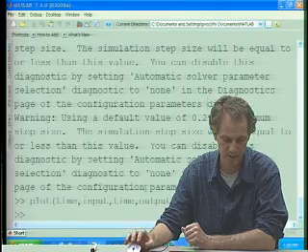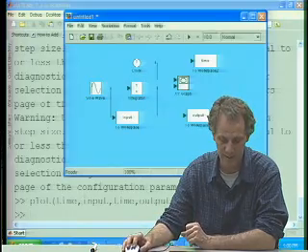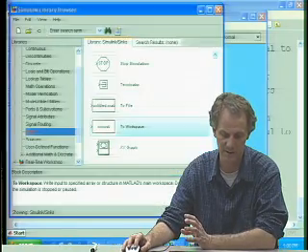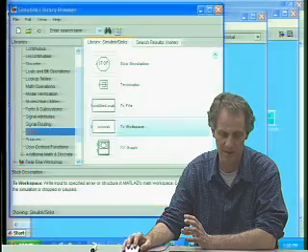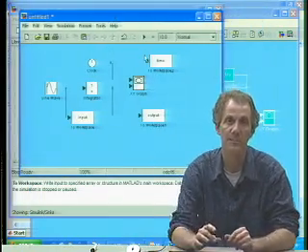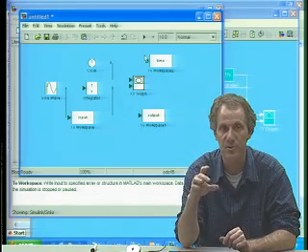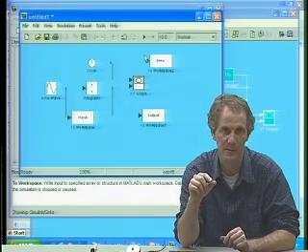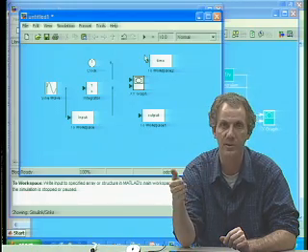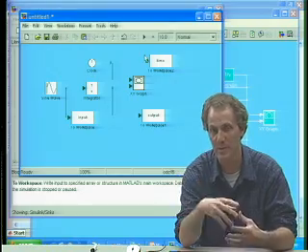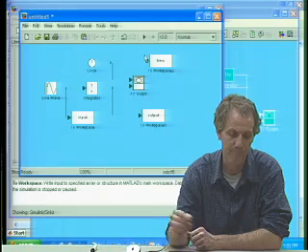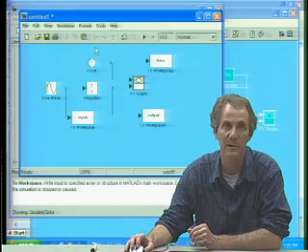So that shows that it can do the integration. It's really not doing, as far as I know, much at all symbolically or exactly. What it's doing is numerically, it's doing it numerically using tiny little steps. And you can control how small the steps are in the numerical integration. You can specify the tolerance of that integration. The smaller the steps, the better, but if you get carried away with that, it can take a long time to calculate. So anyways, there's numerical integration.